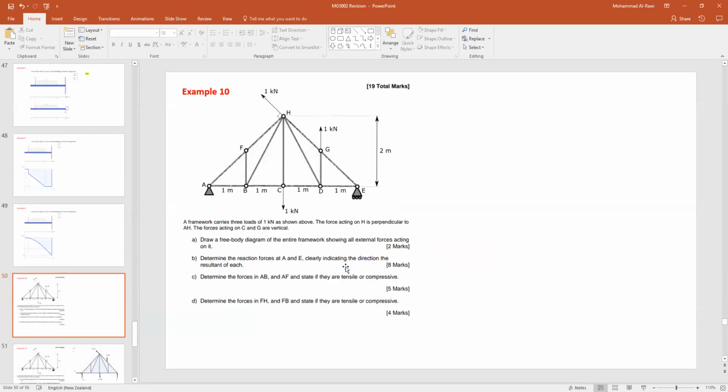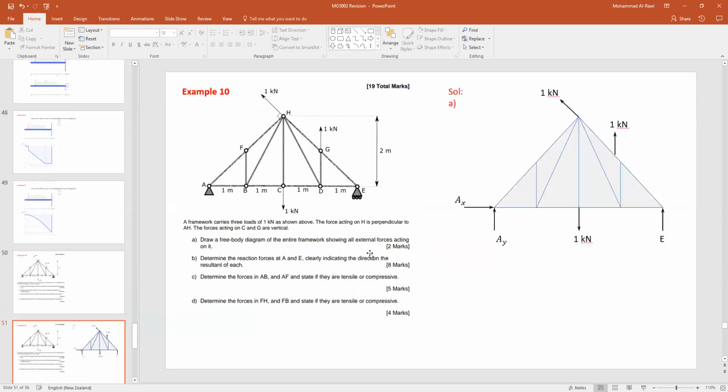One hint for you guys for the exam: when you get this type of question, such as find or draw the free body diagram, if you have this shape for stress analysis, you always draw it and put the external loads on it, and then convert the support reactions to forces, and you will get about 2 marks for this kind of question, as you've seen from the 2017 past exam paper.